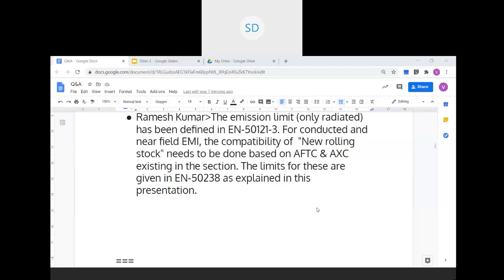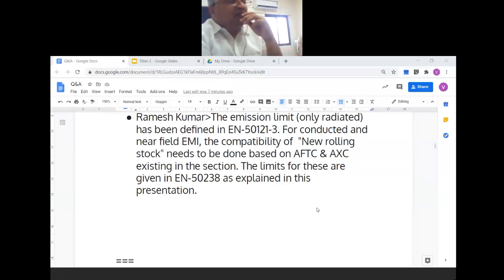Basically, sir, if you see the European railways, even though they adopted the ETCS system, they still have their national systems on their locos also. Every country had their own automatic train protection. So whenever they run the train in their country, if the ETCS is not ready, they will go with their national train protection system, and whenever they enter the ETCS territory, it will switch. So they will have two kinds of sets to read the information from the balises. That is already existing in the European railways. So TCAS and ETCS going together should not be a problem, sir. We should have two sets of equipment, but a conscious decision has to be taken.